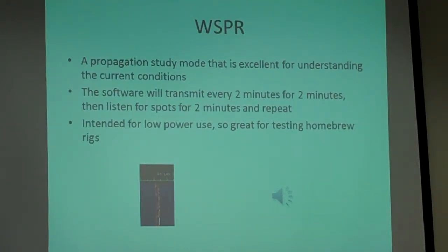But most of the modes are not that simple, and furthermore, what ends up happening is you don't have a clue, in the case of Olivia and Contestia sometimes, how many tones they're using. You can kind of tell, again from experience, that it's 16 tones rather than 4 tones. That's pretty easy. And you can judge the bandwidth based on what the waterfall will indicate, by just doing some simple subtraction.